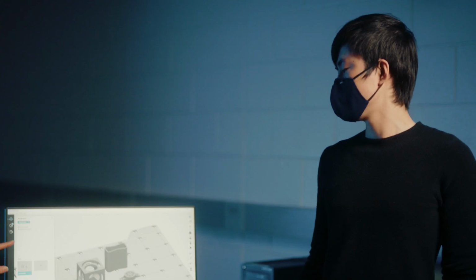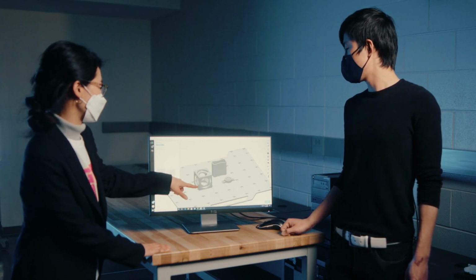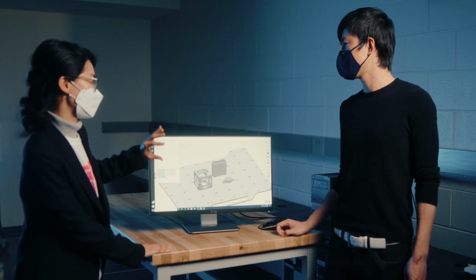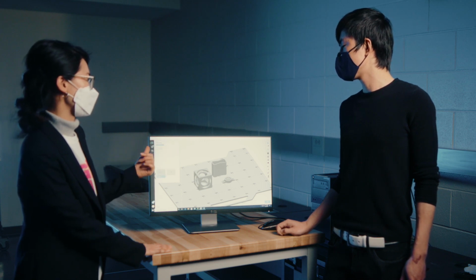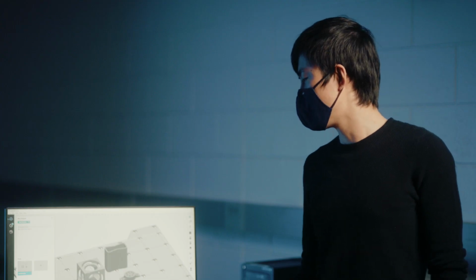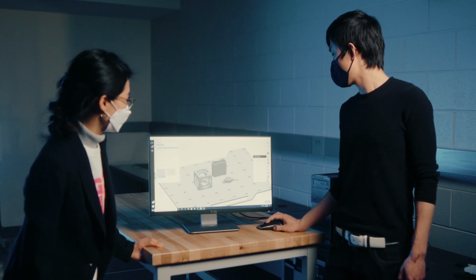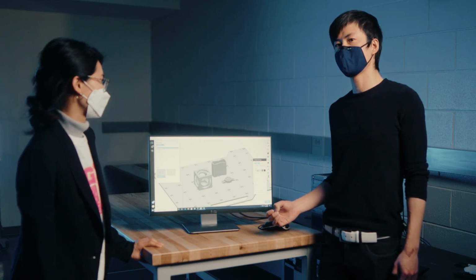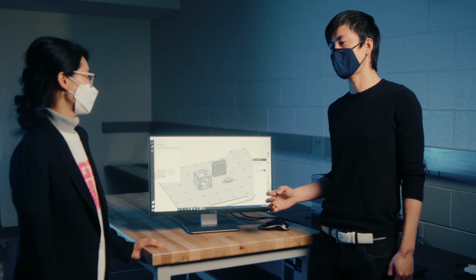I have a question about the setting. You're talking about making the setting for two different materials, like density and different layers depending on angle. So how do you make a setting to increase the accuracy of the 3D printing result? To increase the accuracy, we go to model setting here. There's two ways to do it. In model setting, you can increase the infill, which is how much plastic will actually be printed inside the model.